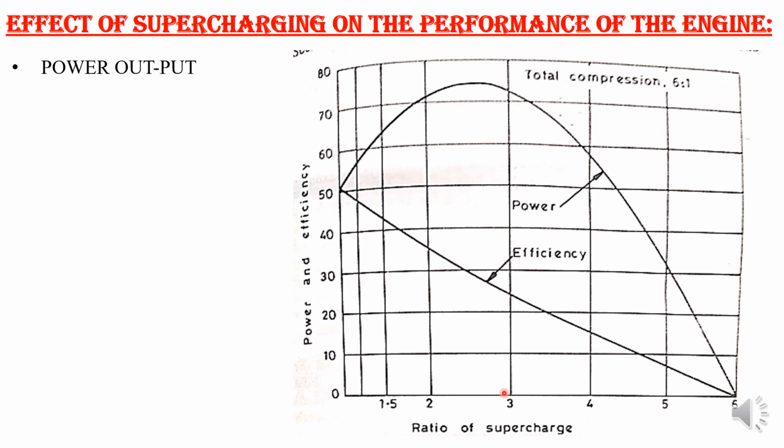So whatever I told above, those effects are common in both petrol and diesel engines. However, in a petrol engine, supercharging results in a tendency to knock. In contrast, a diesel engine will run smoother and is able to utilize a low fuel-air ratio in a supercharged engine. So increased reliability, durability, better fuel consumption, and some other benefits we can get in the supercharged diesel engine.